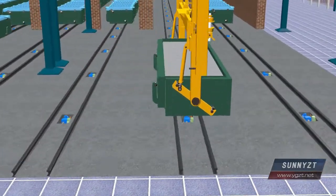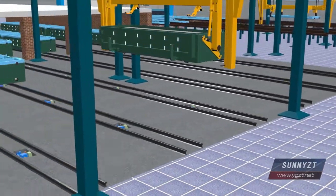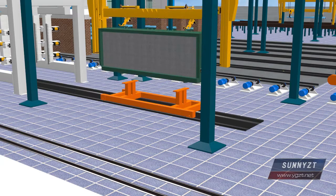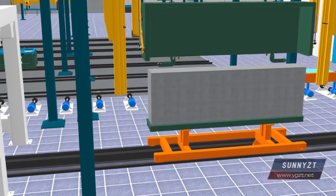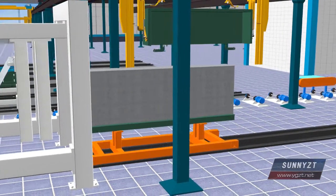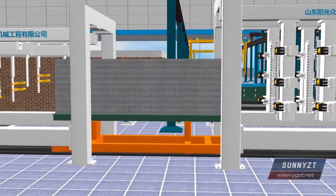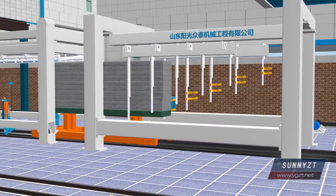Use the reversal crane to hoist the molding box onto the cutting machine. Rotate the molding box 90 degrees to keep it standing sideways on the first cutting trolley. Then, the manipulator of the reversal crane opens the molding frame automatically and does demolding. The first cutting trolley carries the green body and the side plate into the cutting region. Do transverse cutting on the green body in terms of the set width by using the transverse cutting device. Wash the trough on both sides of the green body.